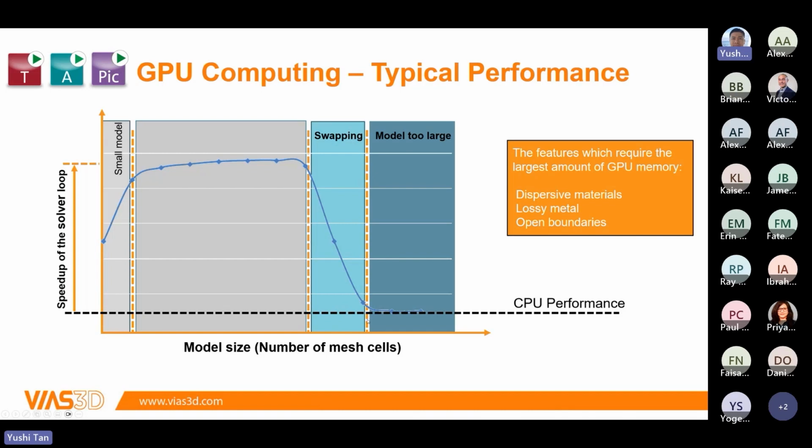Now, this line over here, typically at the 150% mark, where you're exceeding the GPU RAM limit, basically defaults back to the CPU performance. Of course, you're talking about reduced performance. So this is at 150%. It's going to give you a sense of what it is, but you never want to get close to it anyway. Hence the general guideline that each gigabyte of GPU RAM allows you to solve around 8 million mesh cells. That way you can still get the best performance out of your GPUs.